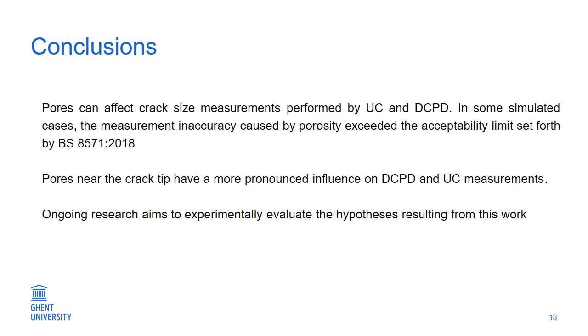The following can be concluded from this work. Pores can affect crack size measurements performed by unloading compliance and DCPD. In some simulated cases, single pore simulations, the measurement inaccuracy caused by porosity exceeded the acceptability limit set forth by BS 8571. Pores next to the crack tip have a more pronounced influence on DCPD and unloading compliance measurements.